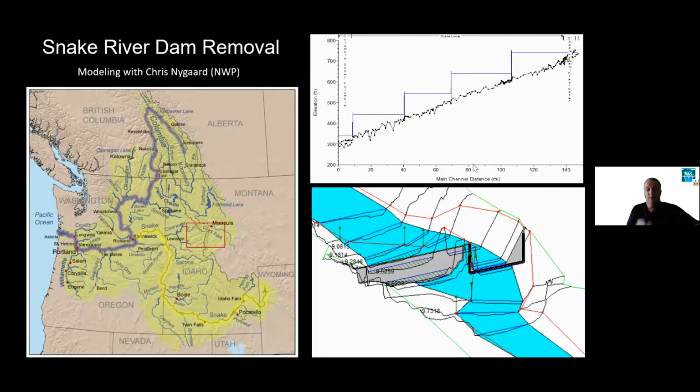We put these dams in, and we calibrated them, and then we calibrated this model to deposition, and we looked at the deposition over the course of the decades that these dams have been in. But that's not a very useful calibration, because you want to calibrate not just in general, but to the process that you're going to be evaluating. And so in 1992, they actually drew down these dams, and so we calibrated both the bed change and concentration from the 1992 drawdown to give ourselves some confidence that we're simulating not just the model, but the actual process that we're trying to capture.